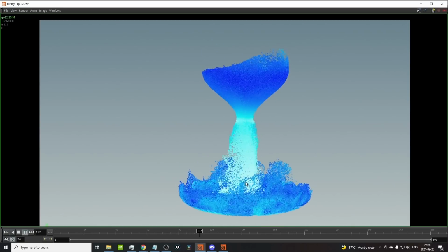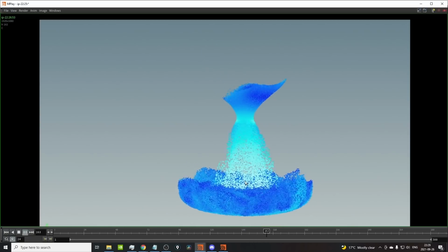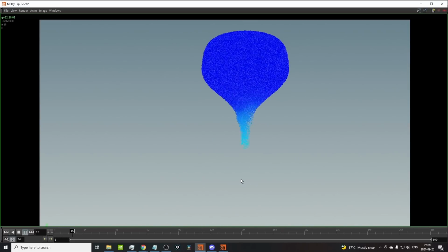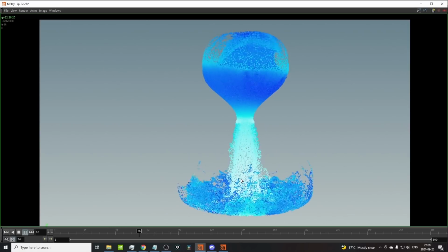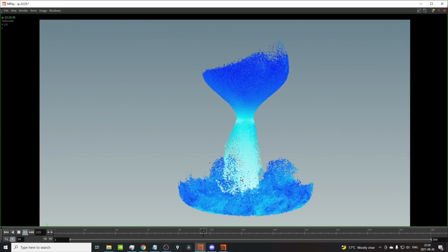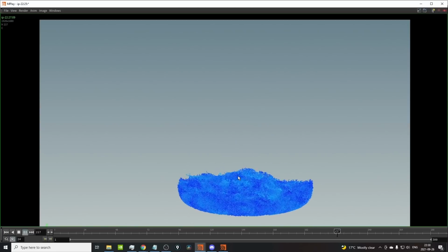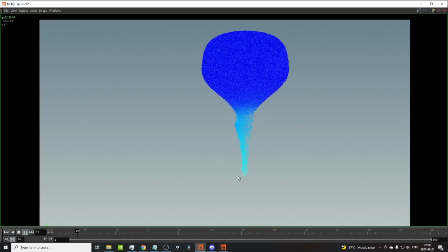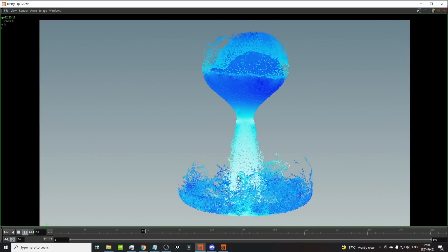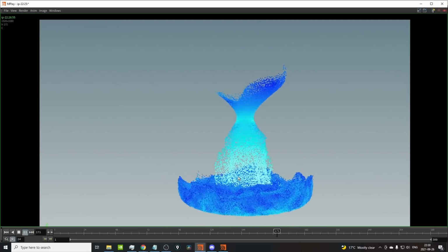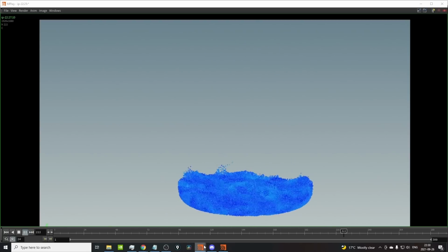So keep this in mind every time you do a simulation and something water levels feel off or particles disappear or get created. Receding is a mixed bag, and sometimes it will work for you and sometimes it just won't. And that's an issue. I personally err on the side of turning receding off unless I know I absolutely need it. So yeah, for most of the scenes we will be doing, I will have receding off from now on, right?